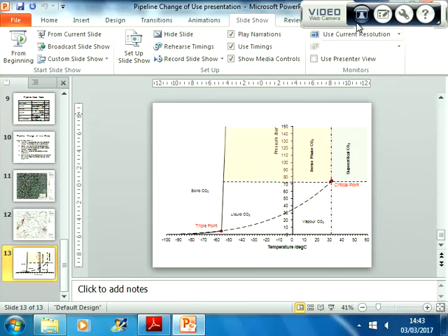CO2 has got all of those, but it's also got what is called the dense phase, which means I don't fully understand it, because it's a chemistry type issue. But what it means is that once you're above these conditions, so once you're above that pressure there, which I think is something like 73.8 bar, it will operate in the dense phase regardless of the temperature.